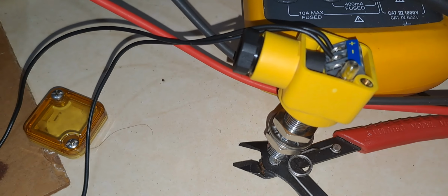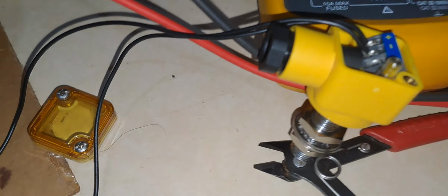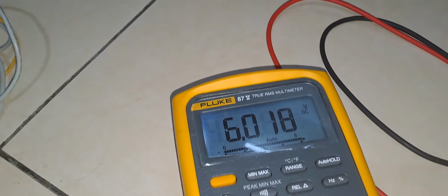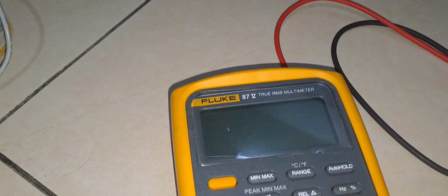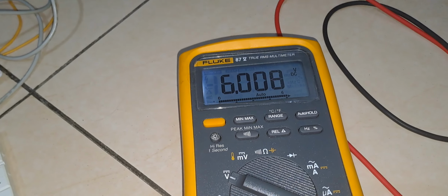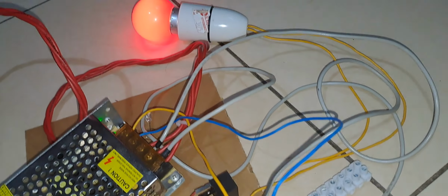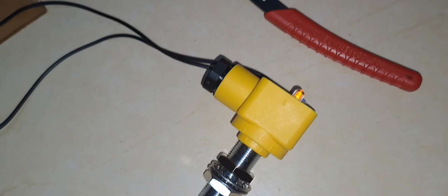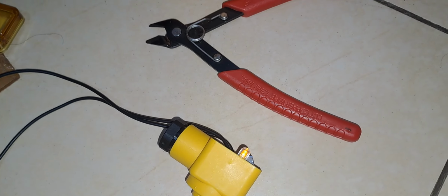Now if I move the switch away from the metal, what am I going to see? See, I have moved the switch from the metal. The voltage between the gate and source of the MOSFET, just a minute, my multimeter has switched off. The voltage between gate and source of the MOSFET is 6 volts. The relay is on and the lamp is on, and there is no object in front of the proximity switch. So this is how the circuit works.